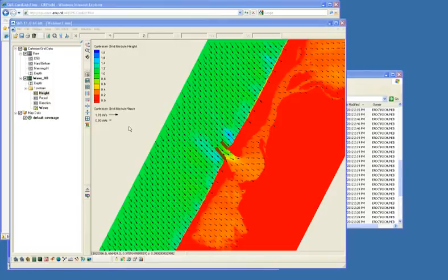One question is, when you begin steering module, the wave and flow grids must be similar in size, larger wave grid. Must the grid spacing be the same? The answer to that is no. The spacing is totally independent of each other. You do want to have a large enough spacing to represent what you need. It looks like Alex has already answered this, but that's not necessarily the case. They don't have to be the same.